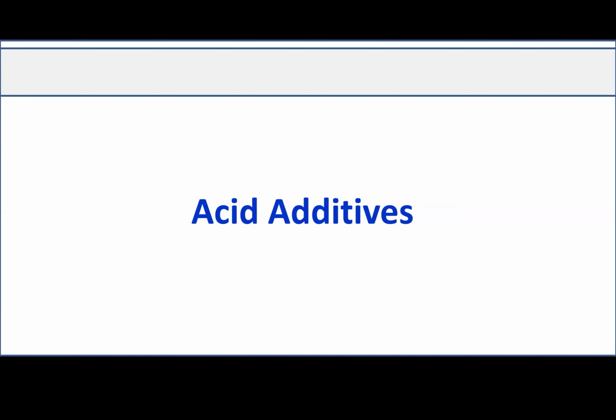There is no damage. But if you find you have a positive skin factor, that's a good indication you have damage. And as soon as you have damage, you start looking back at what the expected type of damage is based on the new well, old well, or injection well scenario, and for each one, try to identify what sorts of damage we have.